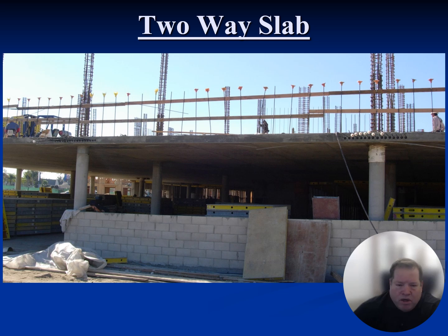That right there is a great picture of why we use post-tensioning, why we do stress checks and strength checks and all the different things that make it a little more complicated than other materials. Nobody can touch us in terms of thickness of material. If you were to take a rebar only deck to go this 30 feet, it'd be at least 10 or 11 inches thick, typically 2 or 3 inches thicker than the PT equivalent. So if you go from an 8-inch slab to a 10-inch slab, that's a 25% increase, which is a lot.